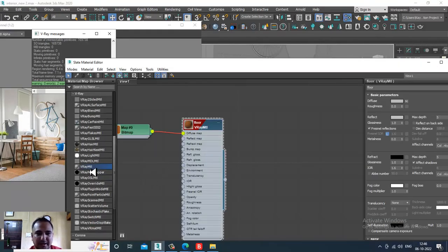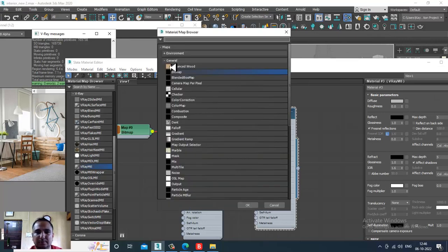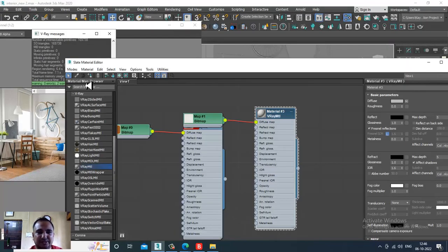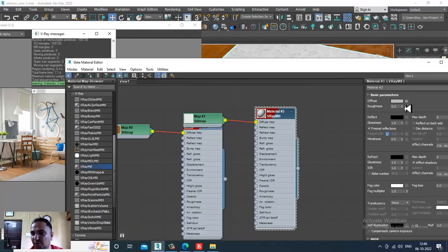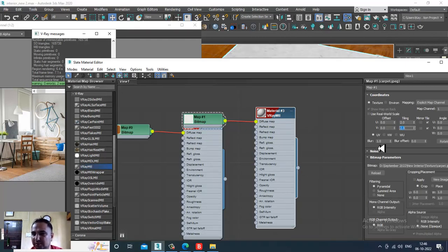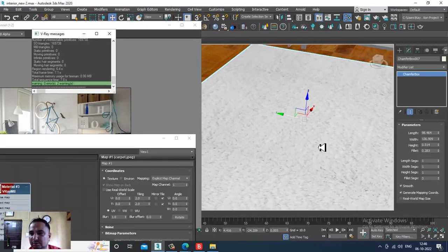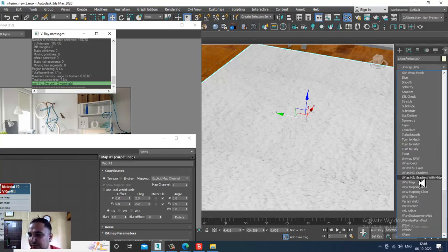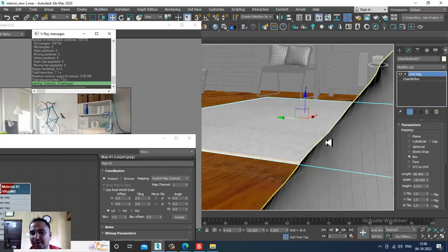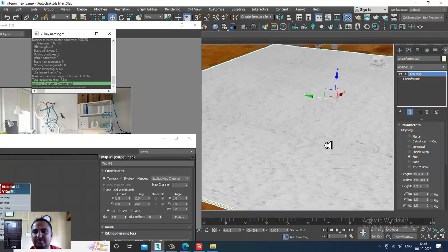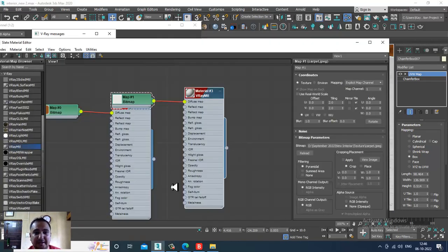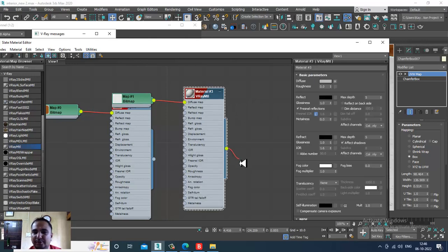So select this. Again take a V-Ray material bitmap. So we have a carpet texture. Let's just assign this. If you want, I can change the texture also. And let's give a UVW map. Set it as a box. We are already assigning the same textures for the carpet, so this time we are going to take some different texture. And in the carpet, I'll again go into this and I'll name it carpet.